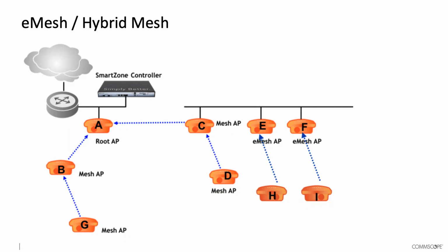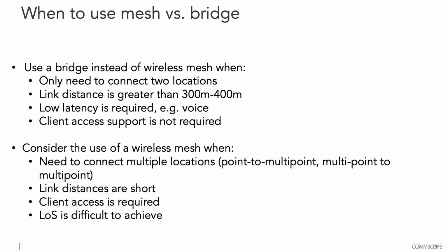For example, I may put APs on light poles, and one AP may mesh to the next. Say I'm using something like 120-degree sector antennas, I'll put them back to back on the light pole, and I can just cable between them. And so every other hop is a wired hop, which means I can change channel every other hop. Being able to provide this flexibility is really an advantage with the Ruckus SmartMesh solution.